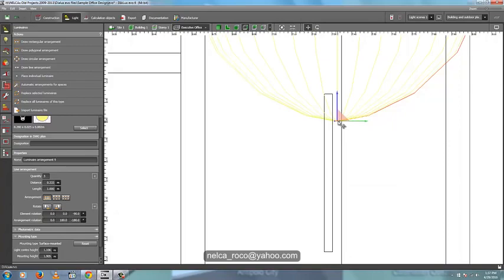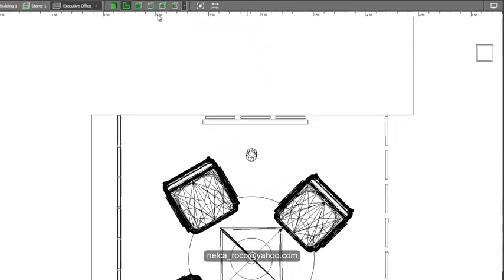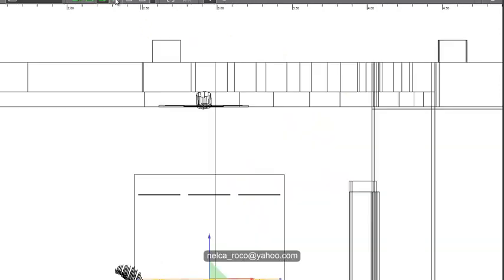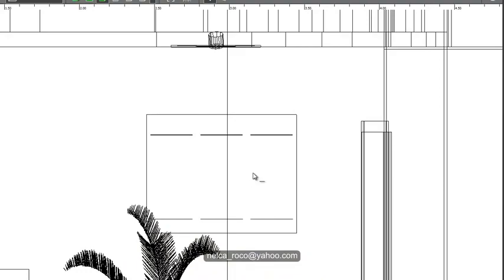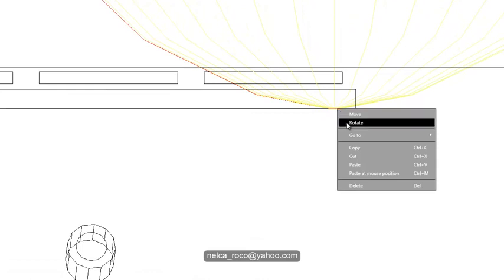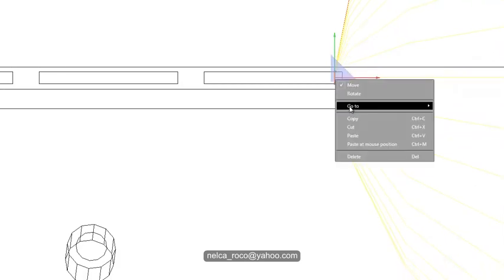And then copy, and then go to the top view and paste, because you cannot paste it in the elevation view. And then move it down, and before it's 180 now, let it be 0 for all. Yeah. And then for the side, you need to create it on the side view. Let's see if it's possible. Draw a line, and let's maybe put 2. It's possible. Okay. And then go to the top view to check where it is located. Yeah, it's not proper, so rotate it and then move. Yes, and then just copy it and paste, and then move it on the other side, and then of course rotate it.